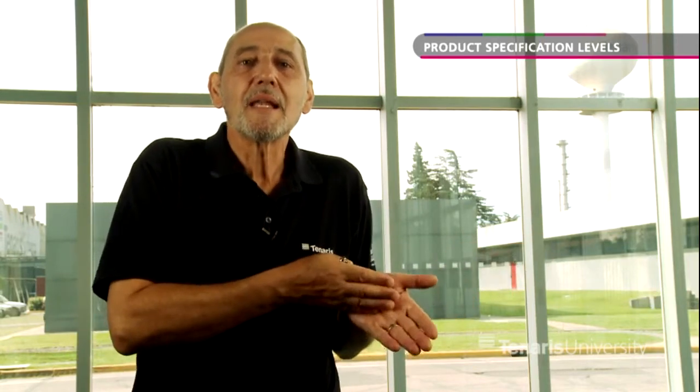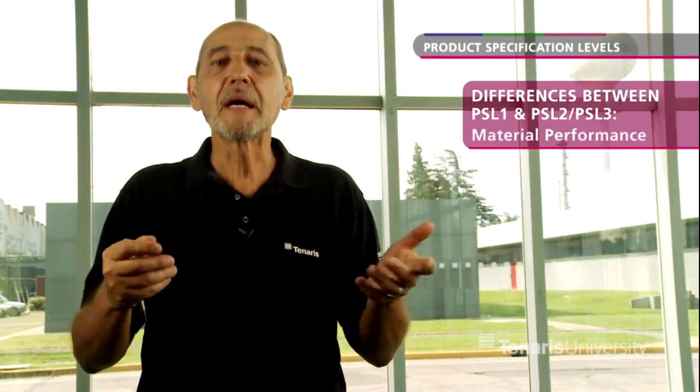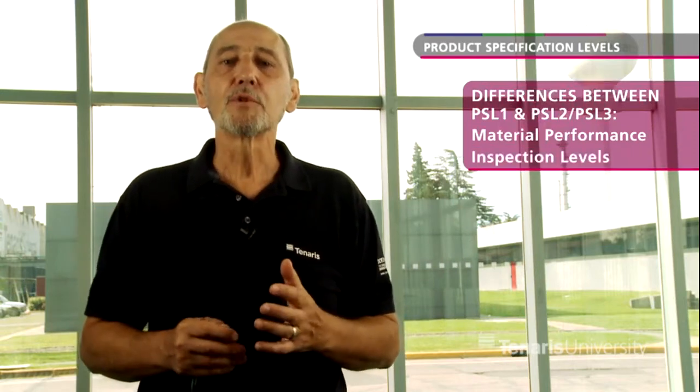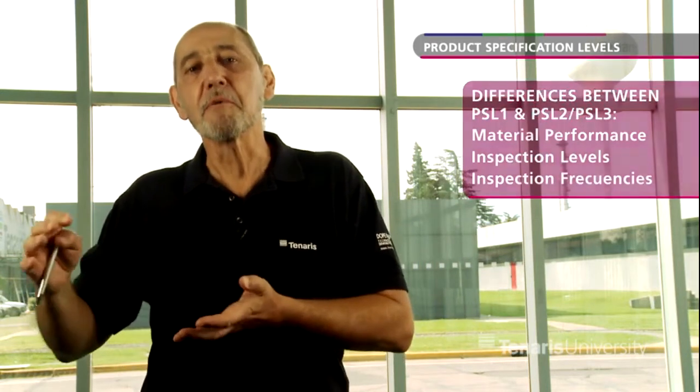Based on this, the OCTG products available today can be specified either as standard PSL1, that is the least demanding, PSL2, or PSL3. Differences from PSL1 to PSL3 are related to the material performance, to the inspection levels, and also to the inspection frequencies.